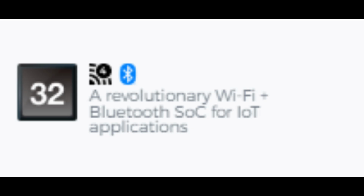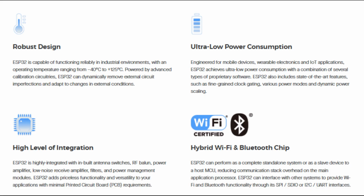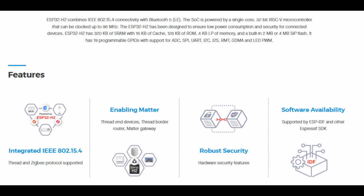Next one is ESP32. ESP8266 has a single core; ESP32 has dual core, with Bluetooth as well as Wi-Fi. And ESP32-H has Zigbee, Bluetooth and Wi-Fi, and is also used for low-power and secure-connection applications.